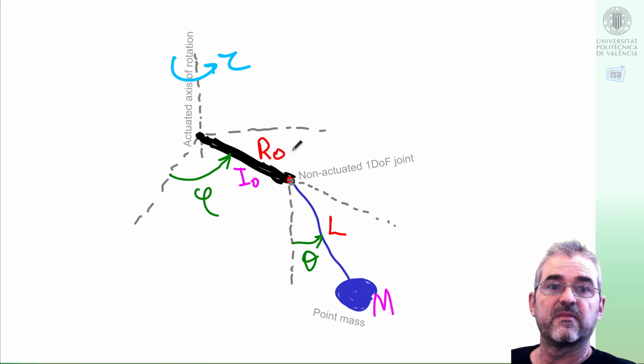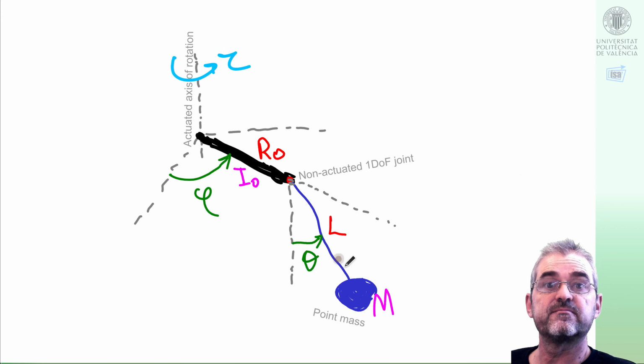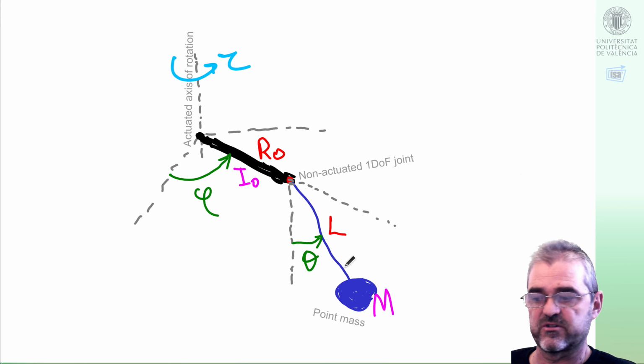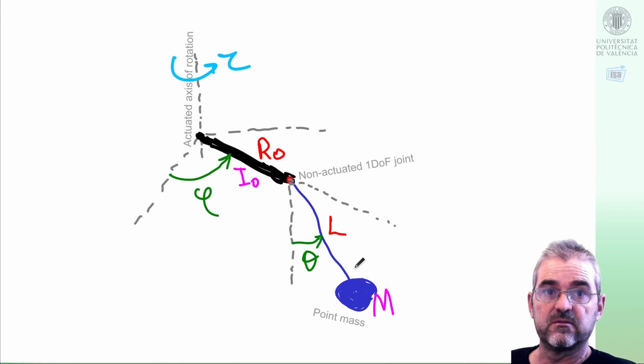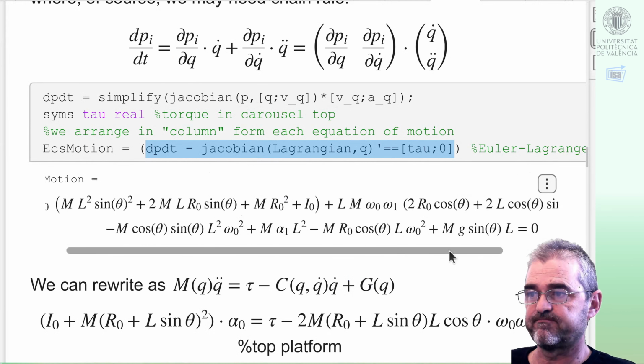Basically, we made an abstraction of the problem as a 2-degree of freedom mechanism in which I could input a torque on this rotation axis to move everything, and then via suitable kinetic and potential energy balances and Euler-Lagrange equations, we were able, with a little help from the Symbolic Toolbox in Matlab, to derive these equations of motion.